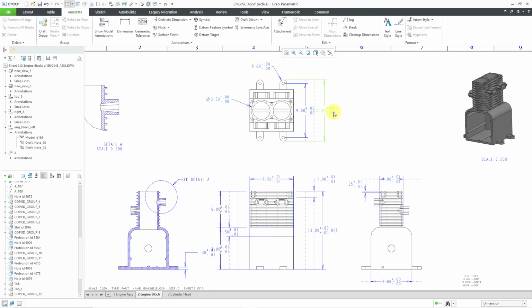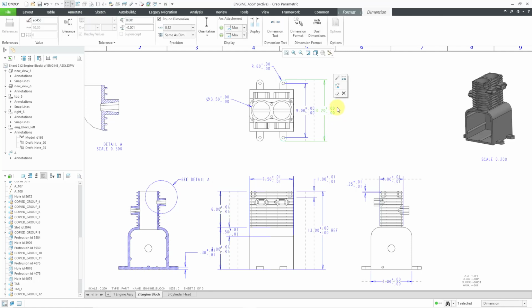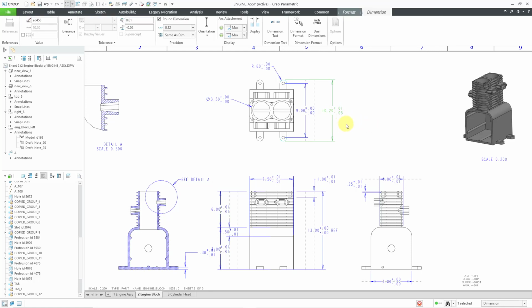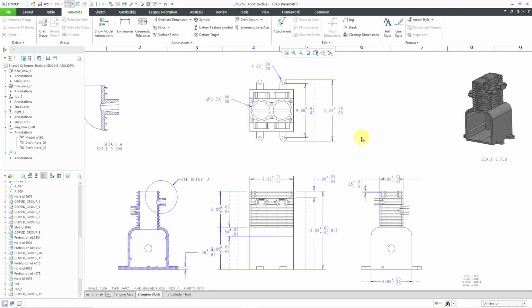And so with some of these different dimensions that I created manually, they are just out to 2 decimal places here. Let me change the value. So for example, maybe this can be up to plus 10 and minus point. Actually, let me make that a little bit bigger. Let's go to 0.1 and then deselect. Did I not actually change that? But try that one more time. There we go. You can change your different dimensional tolerances for these different linear tolerances.